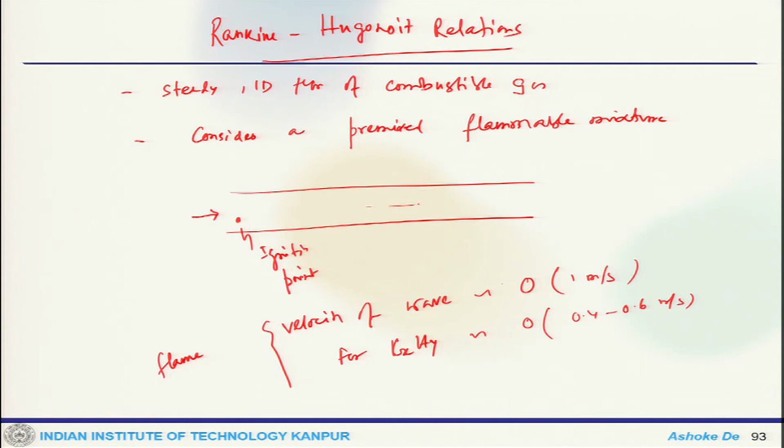Now, once we are talking about the flow property, we call it a deflagration. In the other case, if the tube is closed from one end and then it is ignited at the other end, then the propagating wave will transition from subsonic to supersonic speed under the right conditions. And if that happens, that supersonic wave is called detonation.